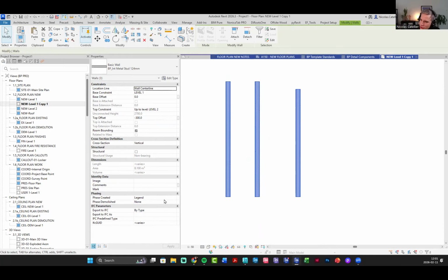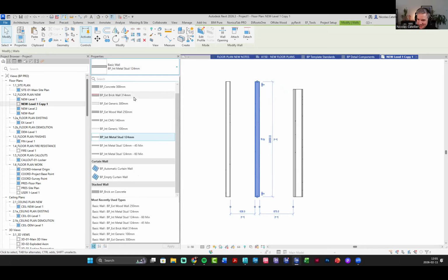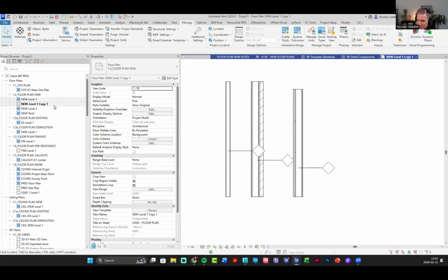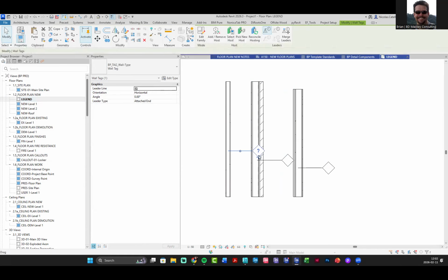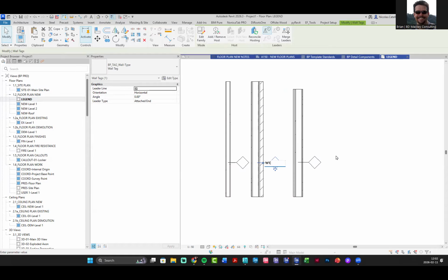Do you demolish them or is it not necessary? I don't. You technically could, so they become temporary objects. But again, if you're seeing the legend phase, then you're seeing a whole lot of other stuff anyway. Yeah, okay. So your legend view would look something like this, and you tag them. Of course, you have real numbers. Even for things like doors, most of my clients want a door legend of, hey, this is leaf type A, this is leaf type B, etc. All of those things are going to be done in a legend too.